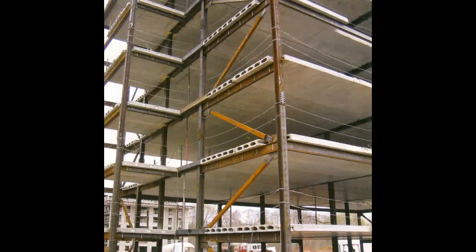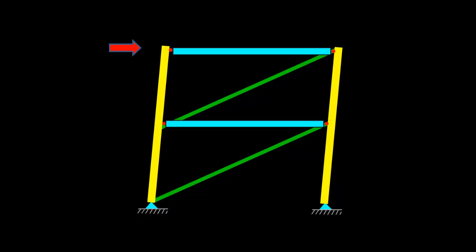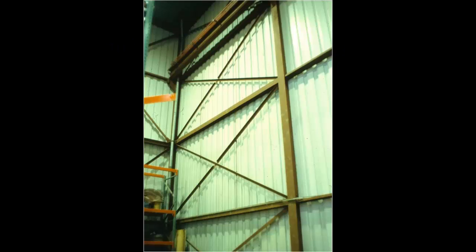Braced frame systems used in buildings are like vertical trusses that cantilever up from a foundation. Here, however, the beams are pin-ended and have bending because they are loaded along their length rather than just at the joints. The diagonals in the frame resist lateral wind loads and provide stability. The columns work with the diagonals as a truss and develop additional axial loads. Braced frames are frequently used for industrial buildings where the diagonals are often tension rods or small angles.